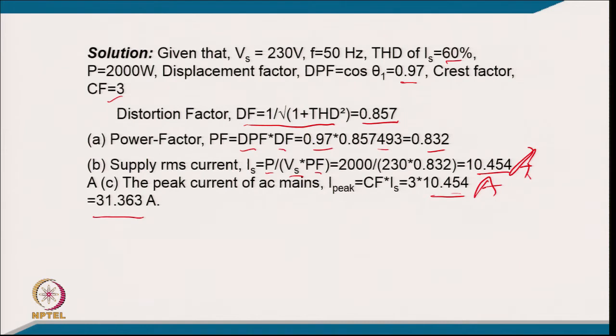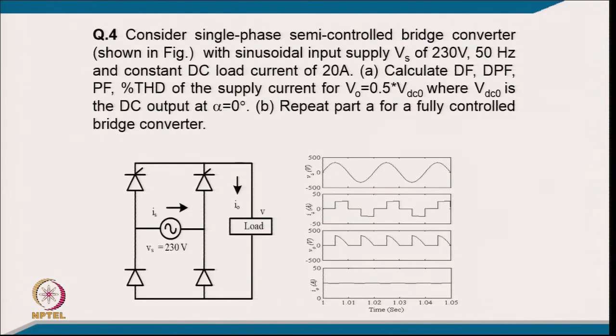Such a kind of load you can call a load with a capacitive end. There are many such loads in practice which have a diode rectifier followed by a capacitor filter, and this THD and crest factor depend on the relative value of the capacitor and the load time constant, meaning the equivalent load resistance.